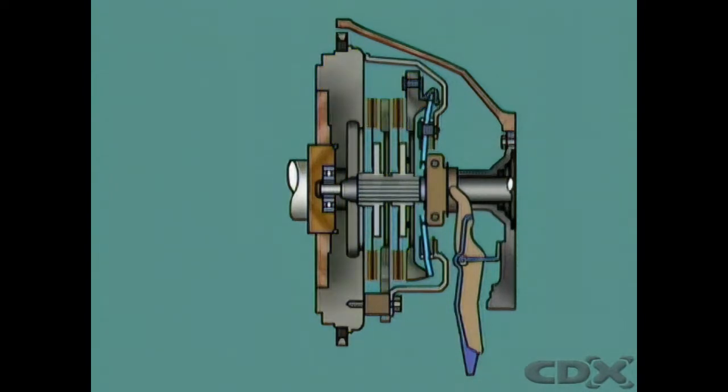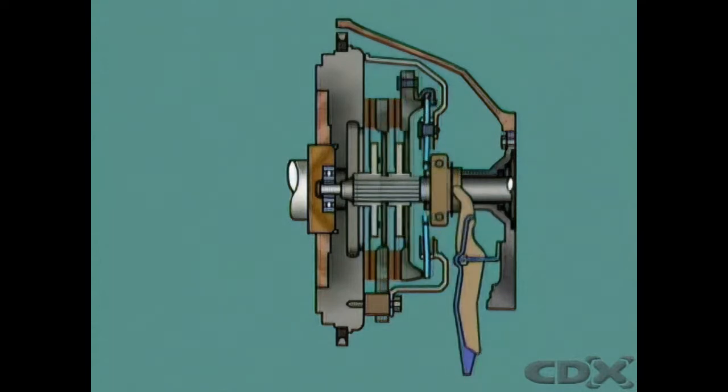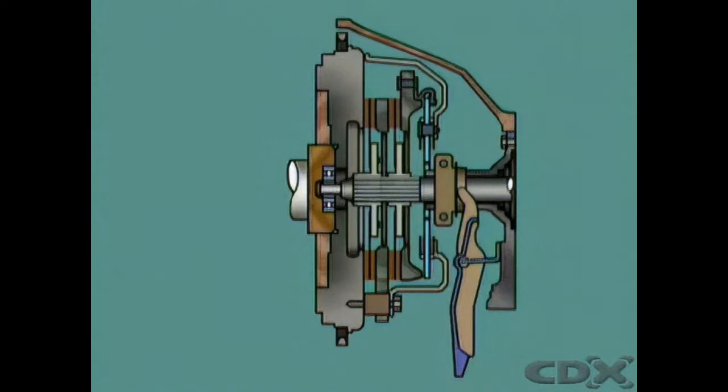When the pedal is released, the spring tension forces the pressure plate, discs, and separator against the flywheel, clamping all components together.